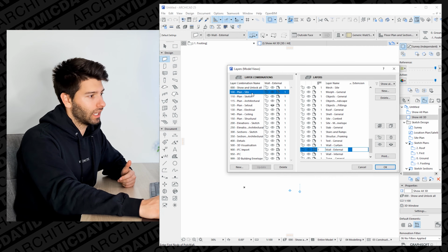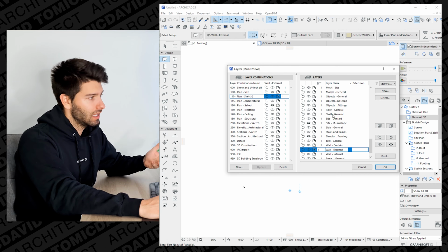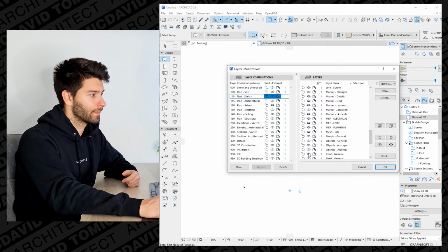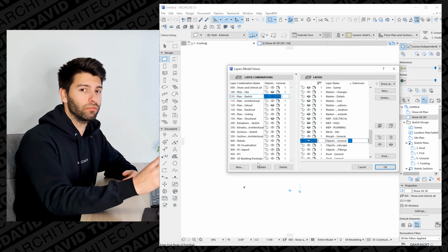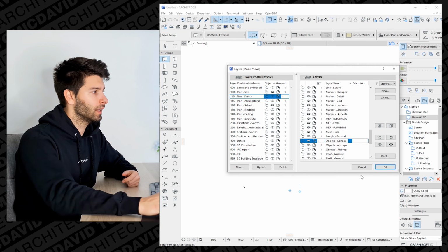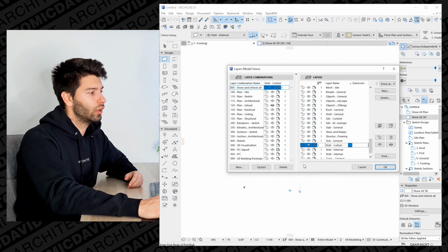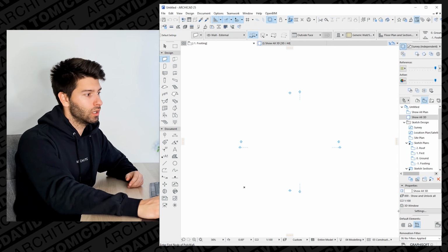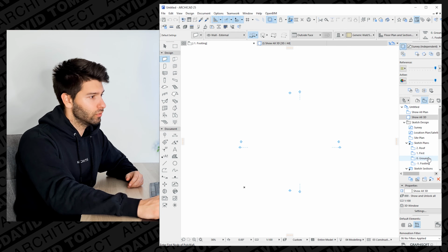So if we were to click on our site plans, this would be activated. If we were to click on our floor plans, that would be activated, and individually we can adjust and change them. If, for example, I untick something, we can update that model view so it automatically updates it for everything. The alternative method to that is pressing Control L again, turning off the one thing we don't want to see just specifically in that view, pressing OK, coming down to that individual view's settings.